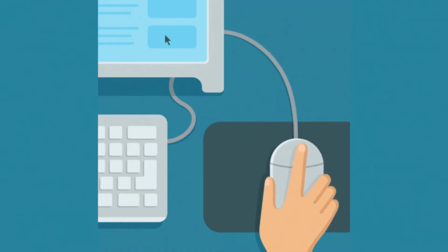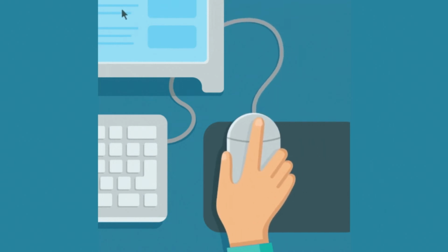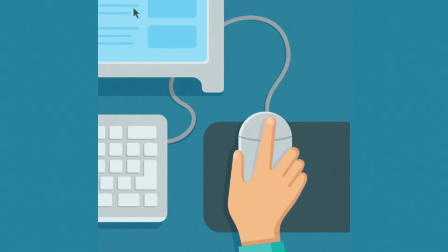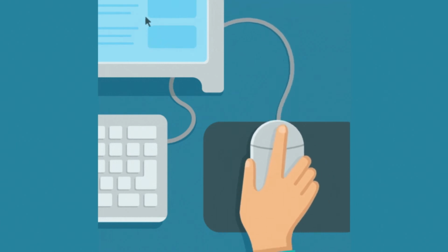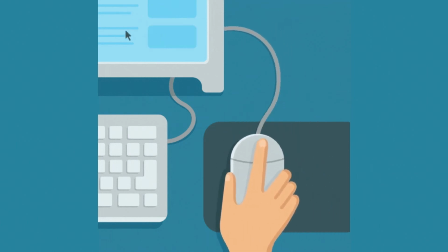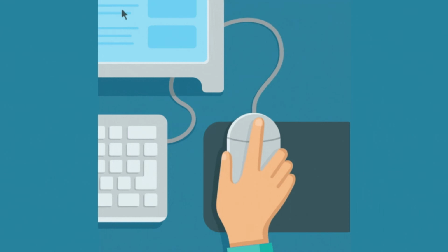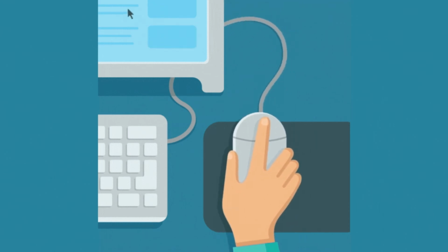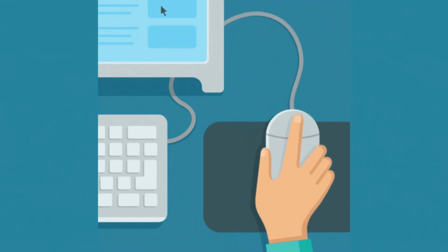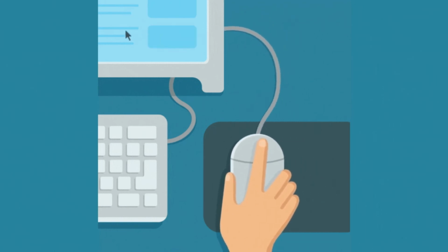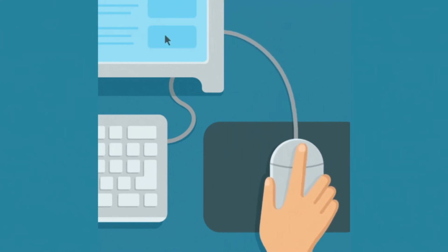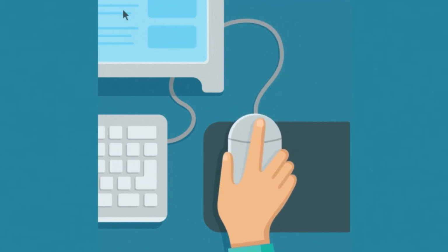Consider a computer that needs to determine whether a USB cable is plugged in. When you plug the cable of a mouse into a computer's USB port, circuitry in the mouse uses the voltage provided by the port to pull up the voltage in the cable above 3.3 volts. In the computer, a transistor detects the high voltage and translates it to 1 or on. This bit of information tells your computer that the USB device is plugged into the port.